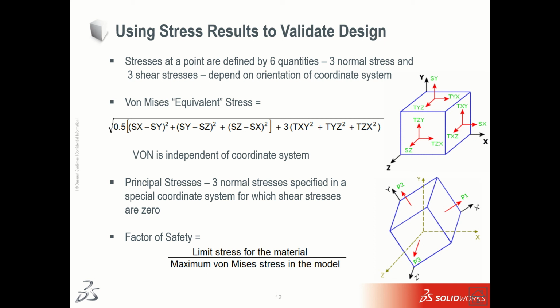But for calculation, meaning in FEA software, we go for von Mises stress, which gives more accurate results than maximum shear stress theory, and it's used for ductile material. While the other method is the maximum principal stress theory, where only the three normal stresses are considered, and if you put the shear stress as 0, then you will get only the normal stress formula under the square root. So this maximum principal stress theory you can use for a brittle material.